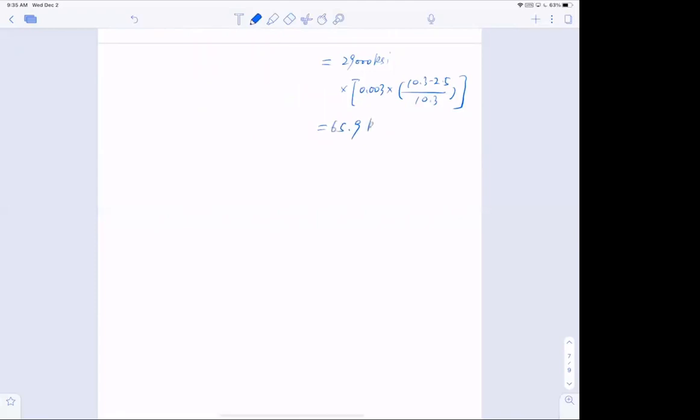ksi. Now, when you see this number, alarms start going, because this is bigger than the yield strength of the steel. But this is okay. This is only in columns. So in columns, we can use Fs prime equal to Fy equal to 60 ksi.